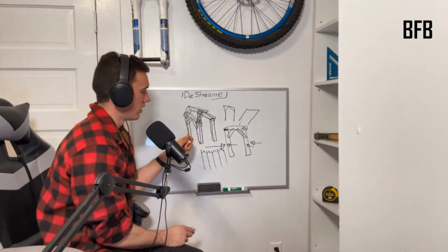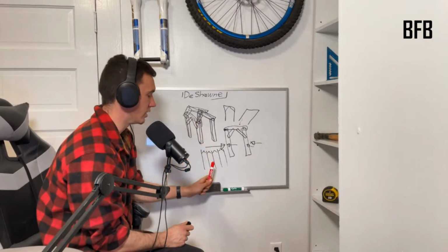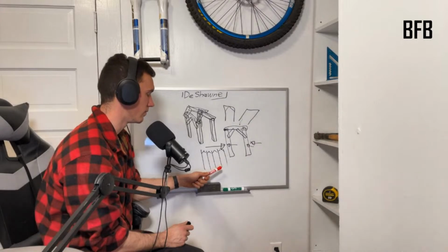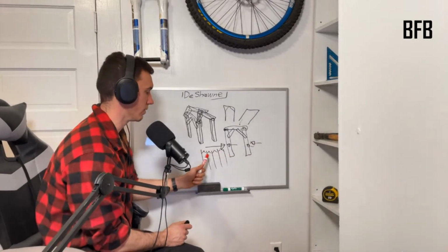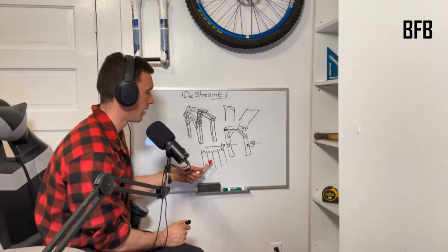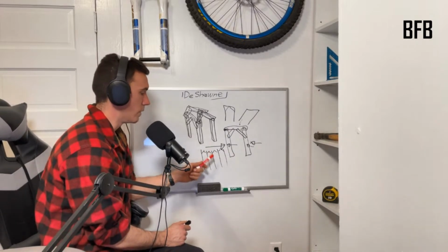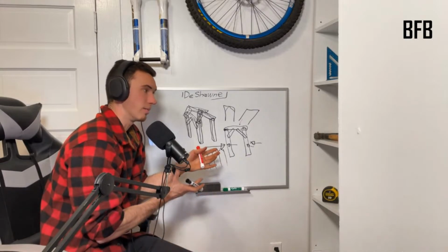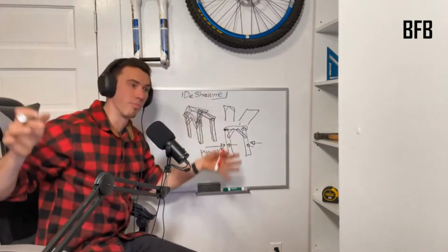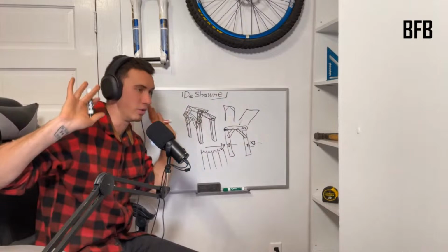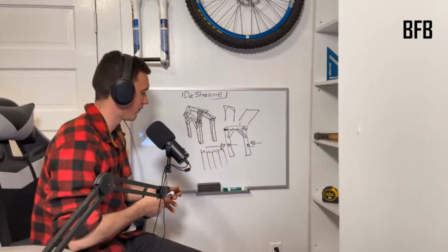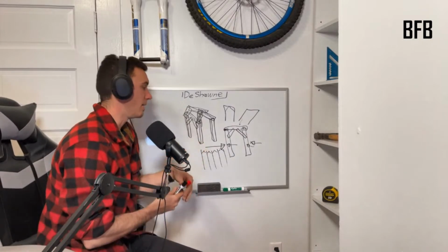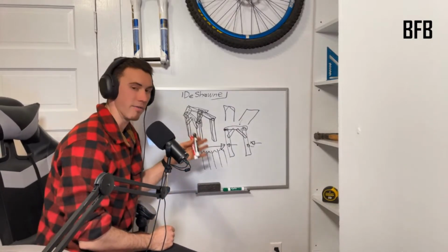So the diaphragm is the combination of the studs or ceiling joists or whatever repetitive member is in the wall doing most of the gravity bearing weight or whatever. And we combine it with usually a sheathing product. Sometimes you can use like gypsum board, but generally it's a board product. It's a big flat thing that you're going to nail to all the studs and stuff like that. So the combination of those two things makes the diaphragm.